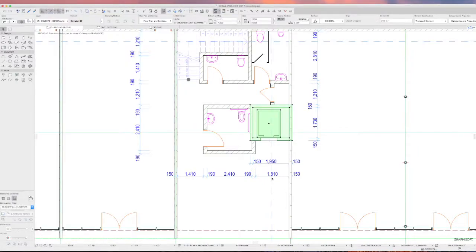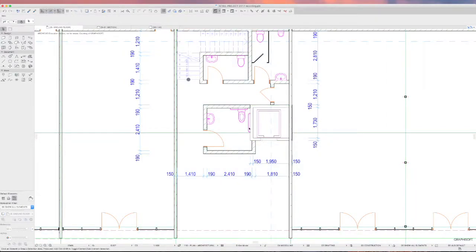So that's why I decided to do concrete tilt-up walls all the way around, which is probably better in modern elevator practice. Conventionally, years ago, the first call probably would have been concrete block. But these days the elevator manufacturers would prefer a higher tolerance finish for the inside of their shaft, which you can probably get better with concrete tilt-up or preformed panels of some sort. And the only way I could do this also is to bury the right-hand wall into the concrete tilt-up wall, so it laps over the top.